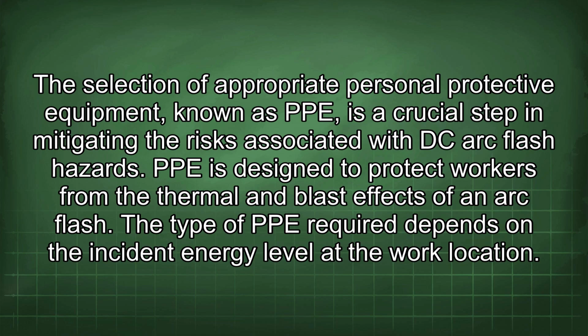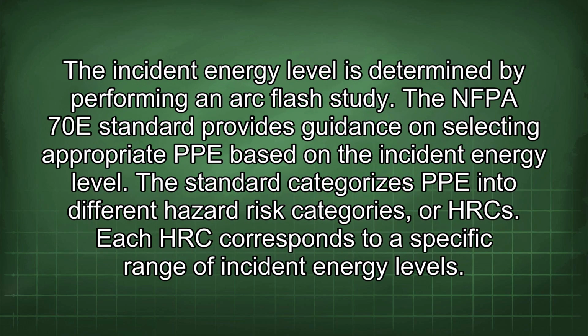The type of PPE required depends on the incident energy level at the work location. The incident energy level is determined by performing an arc flash study. The NFPA 70E standard provides guidance on selecting appropriate PPE based on the incident energy level. The standard categorizes PPE into different hazard risk categories, or HRCs.